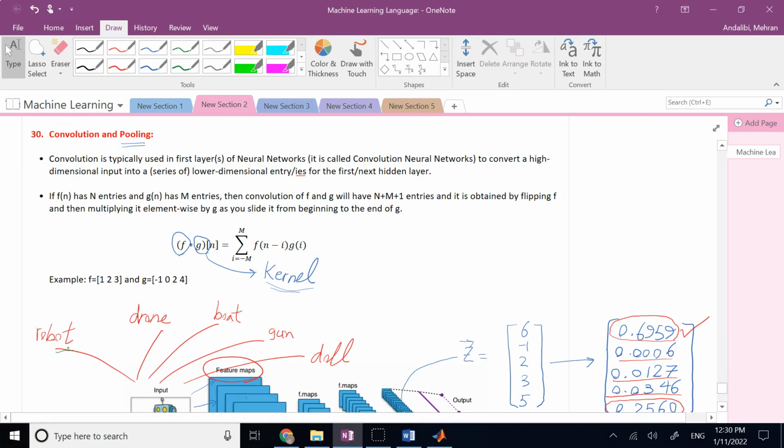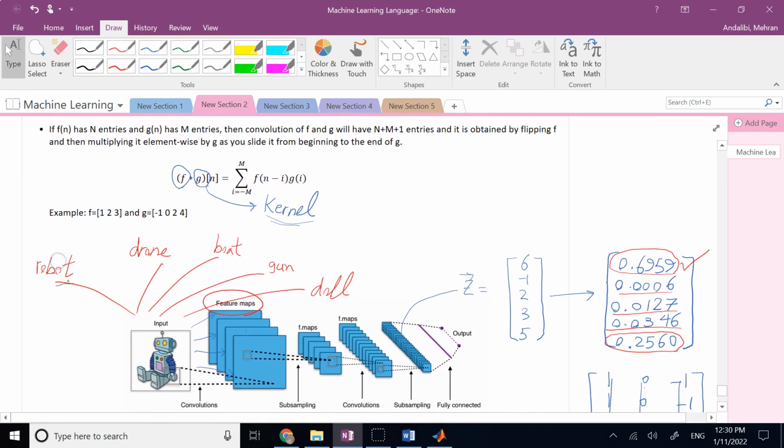And here, to clarify it for you using formulas, an example. First, if we go over the formula, the convolution of two discrete limited signals f and g, and when I say discrete, it means they are not continuous, they are only a bunch of quantized values, and there are only a few numbers in each one of these vectors f and g, not an infinite number. All you need to do when you convolve two sets of data is you flip one of them, and then what?